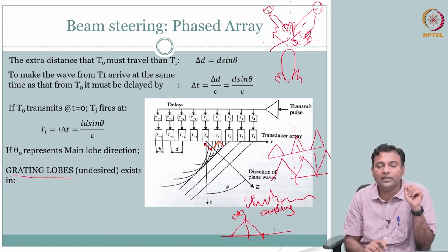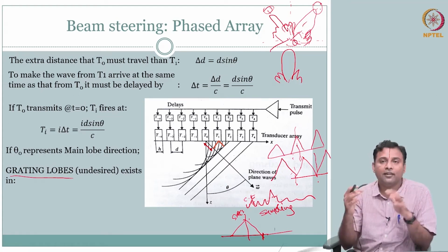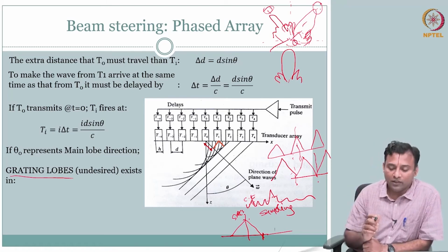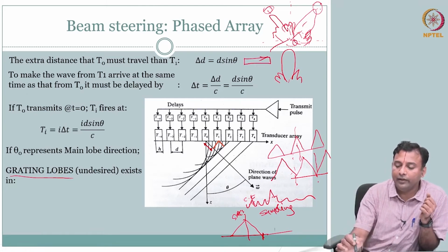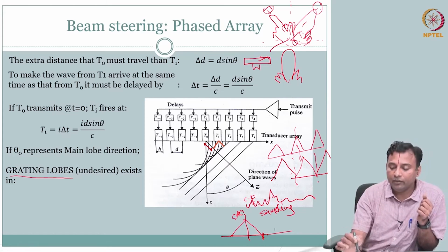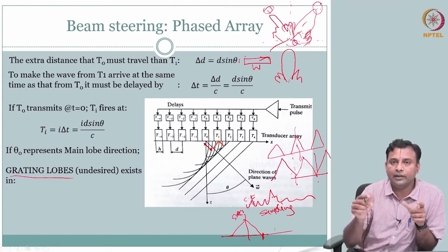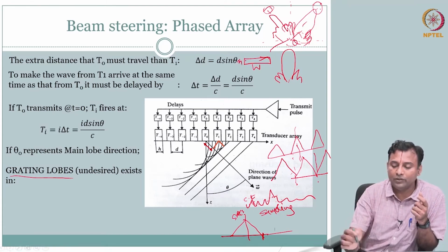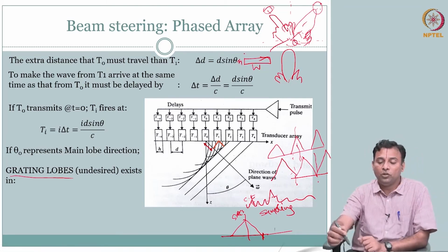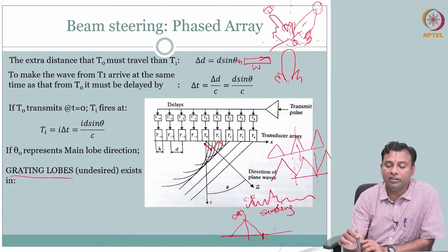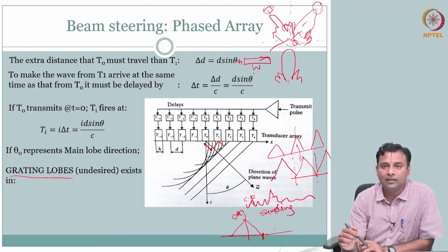However, here what are we sampling? In imaging it's all about space. Now imagine what we covered so far for main lobe and side lobe is just one transducer, right? We had a width, and let's not worry about elevation. So there was some height, so don't worry. If you look at the rectangular transducer that we put through the beam pattern, let's just take the width, which is in our imaging plane.